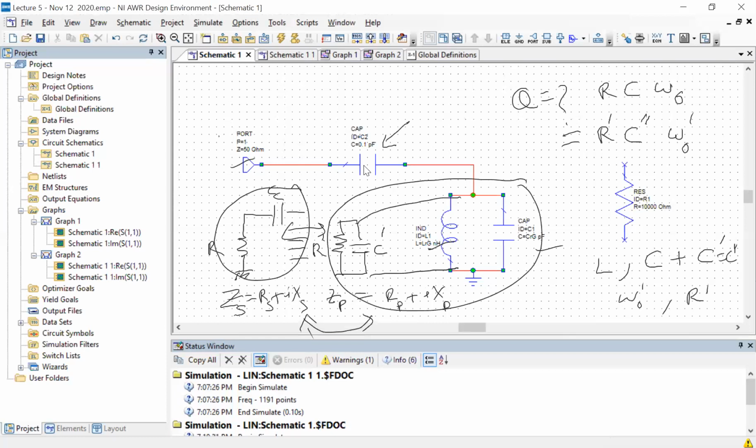So the assumption here is that this is a model which is local in frequency. It only works at one frequency, to be more precise, but for small changes of frequency it's a good approximation. And what is the correct frequency to use? It's the resonant frequency, because we are always assuming, as I've mentioned earlier, that we want this capacitance to be very small so that the frequency shift is very small, because we want high Q factors.